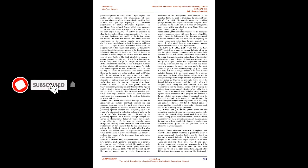Kalu and Mirzabazorg, 2003-5, have additionally conducted analyses of simply supported skewed bridges with concrete decks and five precast prestressed concrete I-girders. Span lengths, skew angles, girder spacing, and arrangements of internal transverse diaphragms were the variables. Bridges with no diaphragms and with different arrangements of internal transverse diaphragms were considered.